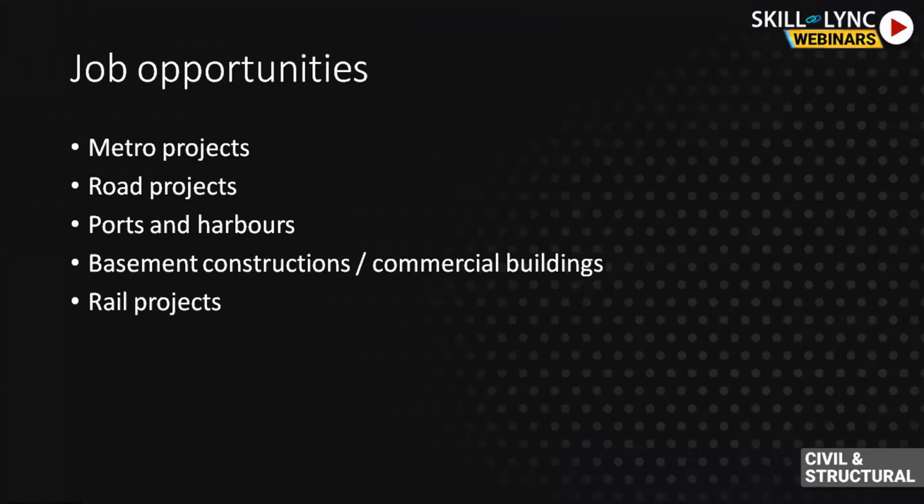And basement construction: when we are constructing a commercial building, nowadays there are many buildings which have basements of minus 3, minus 2 below the ground level. For these constructions, you have to understand the embedded retaining concept. Embedded retaining walls are predominantly used for the construction of these underground projects.